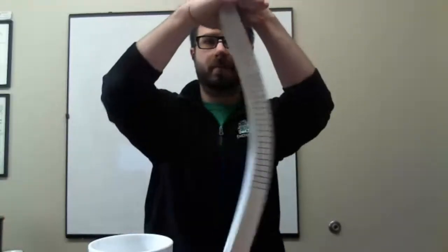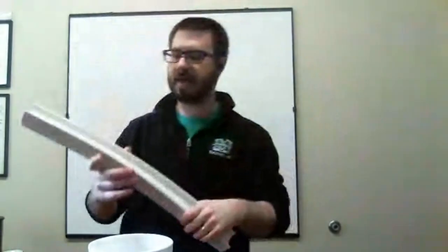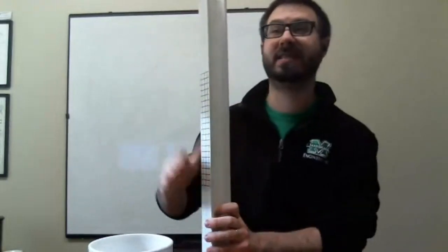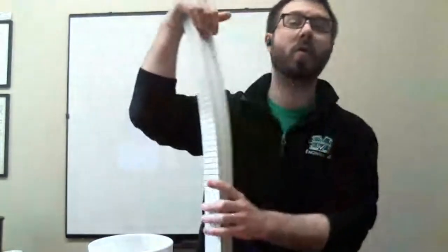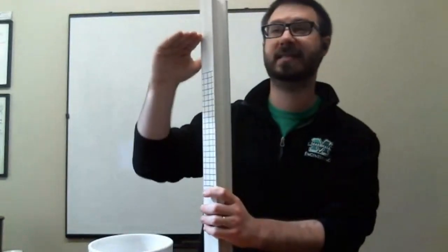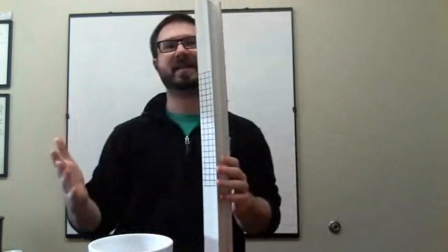Another limit state might be compressive buckling. Here's the column, bam, it buckles. For each of those limit states, I might compute a capacity. What is the capacity of this element before it buckles, or before it reaches its capacity under yielding? So I've got these two.